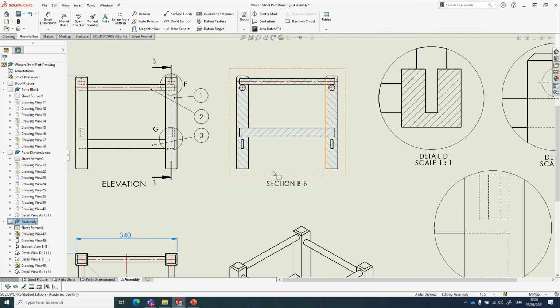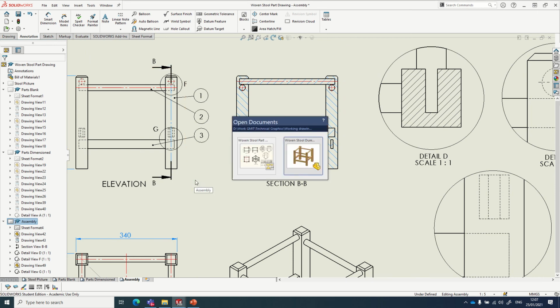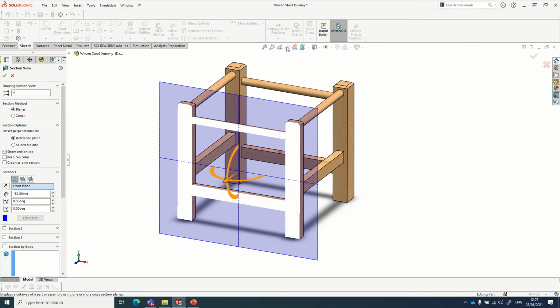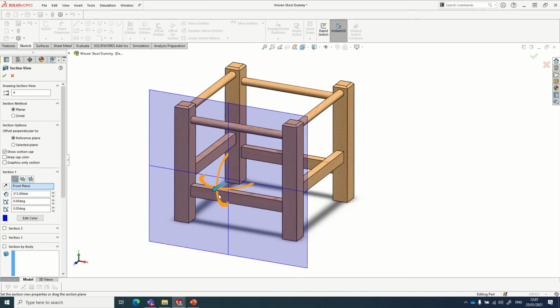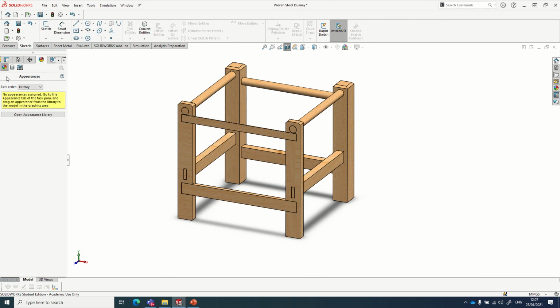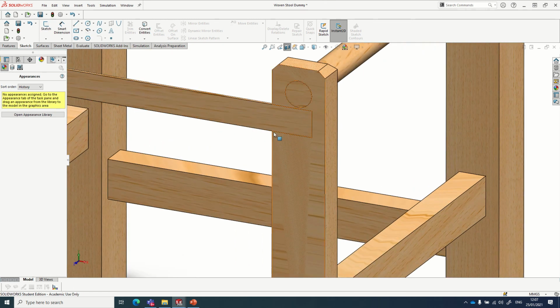our sectional drawing here. So a sectional drawing is basically our piece here with a slice taken through it. If we go back here to our 3D, this here is our section. When we do that, a section is basically cutting through the piece so you can actually see inside it. So instead of looking at hidden detail, we're actually cutting away a portion of the piece to reveal what it looks like inside at a certain section.